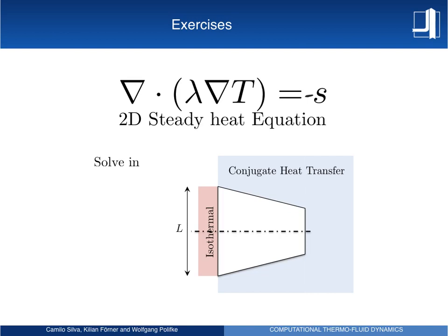But it's just an additional change, not much. You can also describe a lot of different physical phenomena with the Laplacian. So this is a kind of Laplacian. For example, the acoustic equations, the wave equation: instead of T, you have the acoustic pressure, and instead of lambda, you may have the speed of sound. And the speed of sound can change in the domain, so you can actually have the speed of sound varying inside it. So the equation will look actually the same, but now you are describing a different phenomenon.